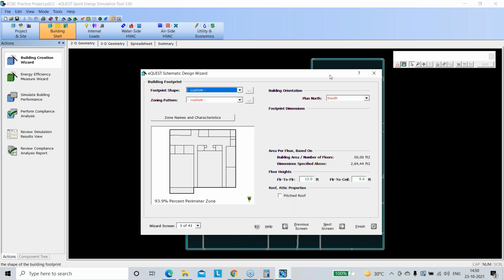So basically, once you do the first standard design simulation, you copy it and make another one, but just change the orientation from 0 to 90 degrees, and then run it, and then again copy it and make it 180. Like that you can get all four orientation energy consumption results, and the average of all those four values will be your standard design orientation.